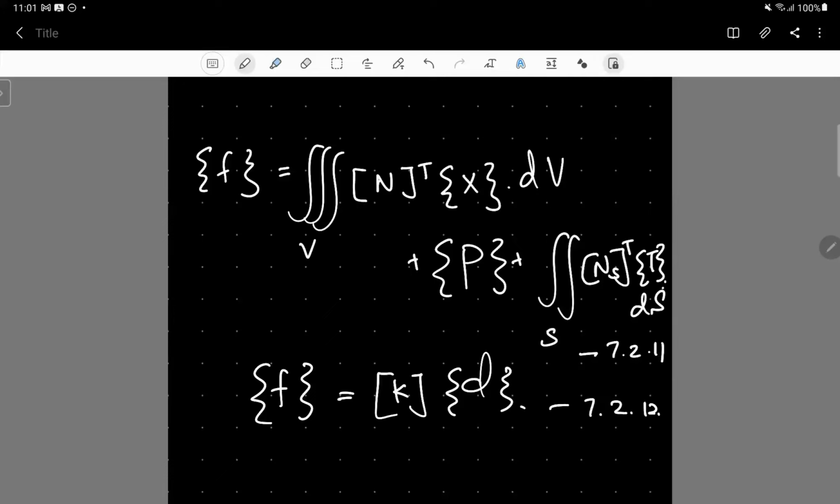The remaining steps for these elements are quite the same, of course, if you can recollect what we did for calculating stresses using the constant strain triangle element matrix. It's important to note that when we consider the rectangular plane stress element, the stresses within this element now vary in both x and y directions. You will realize this when we solve a problem in the next lesson.